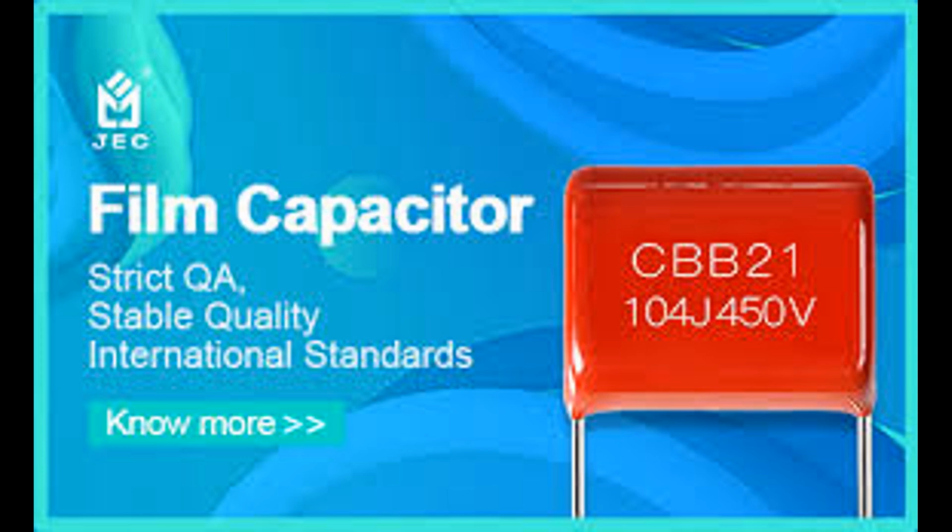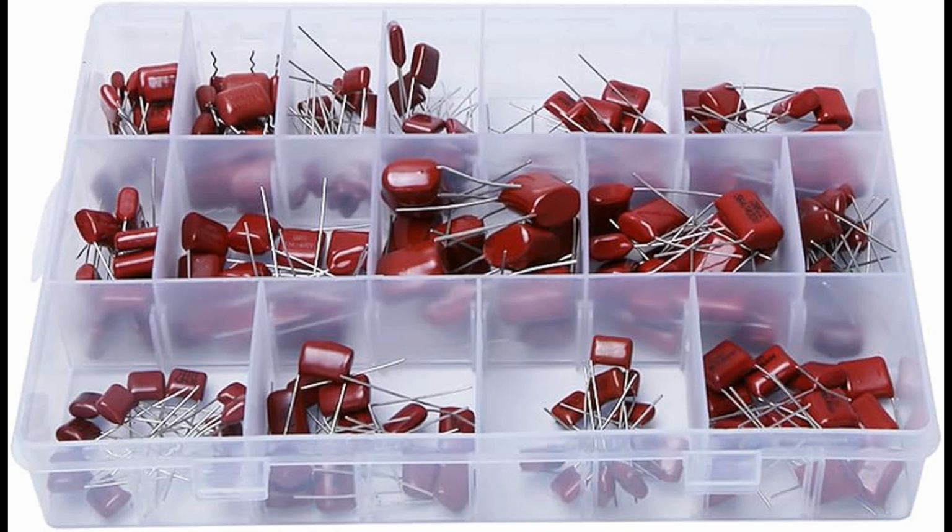Charging/discharging. Capacitors store energy when voltage is applied and release it when the circuit requires power. Dielectric function. The plastic film insulates the electrodes and stores the electric field. Self-healing. Metalized film capacitors can recover from small dielectric breakdowns by vaporizing the damaged part of the electrode. In essence, film capacitors store and release electrical energy efficiently, providing stability, filtering, and energy management in a wide range of electronic circuits. Applications of film capacitors.